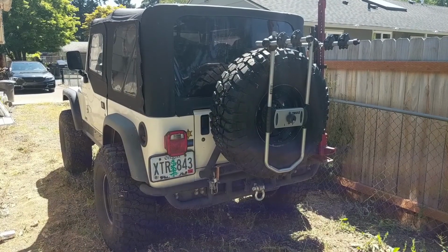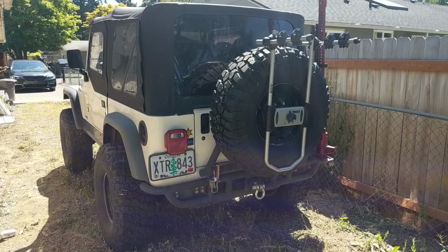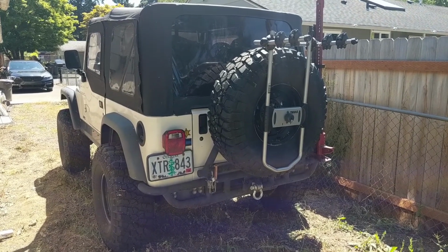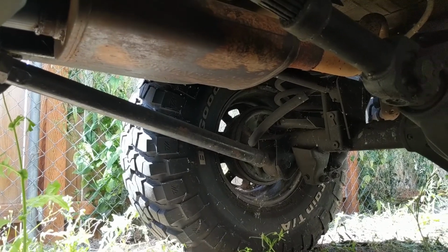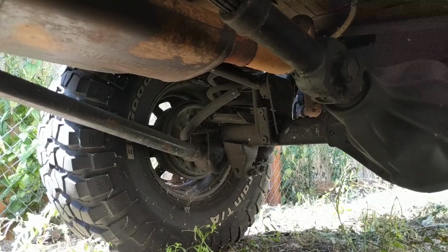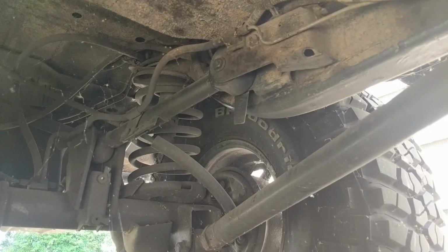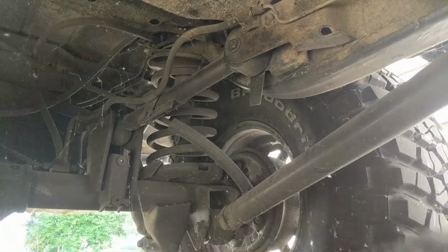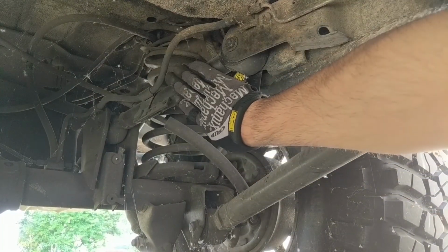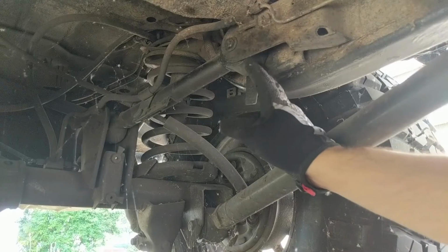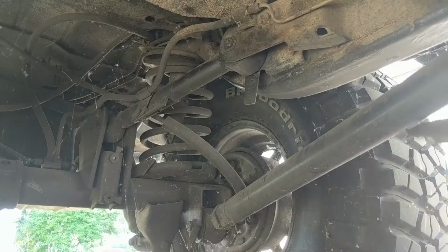For this example, we'll be looking at a 2000 Jeep Wrangler that's had some modifications done to the suspension system for off-road use. Here you can see the lower control arm spanning from the chassis back to the lower part of the axle. This vehicle is using coil springs for the suspension. This is the lower control arm, and up here is the upper control arm. The upper control arm is considerably shorter than the lower control arm.